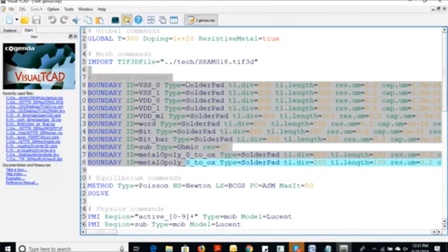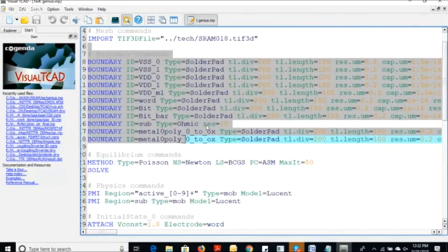For the boundary condition, we have to define a solder pad because our device is passivated. The device surface is passivated, so it will be like a packed chip. If we have a chip, how do we provide biasing? Either we put it on a breadboard or we provide solder contacts. So we use the solder contact pad here. The same approach: solder pad to all the electrodes, and then what signal we want to apply.